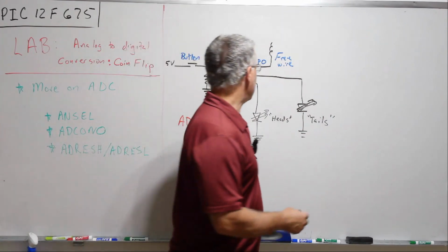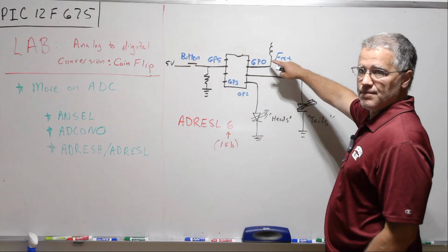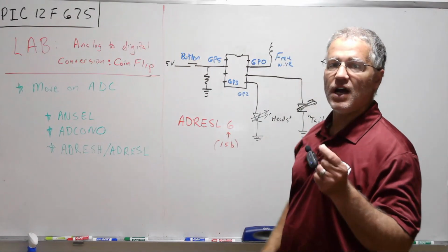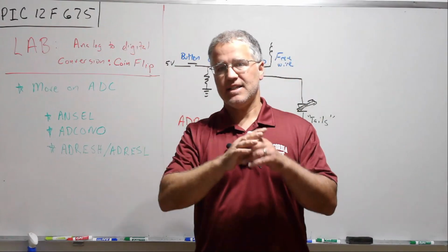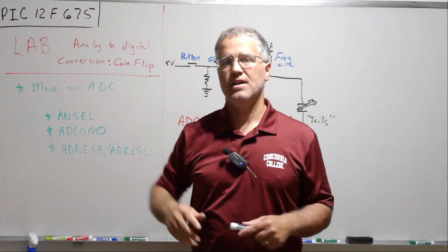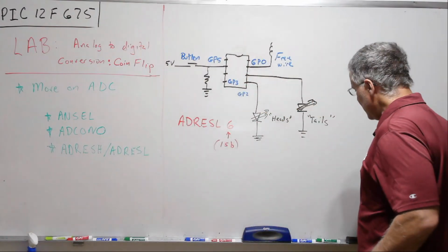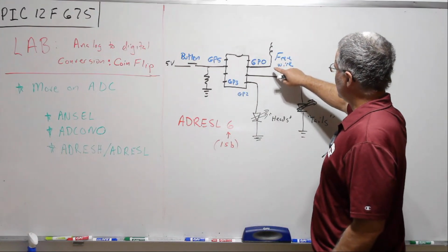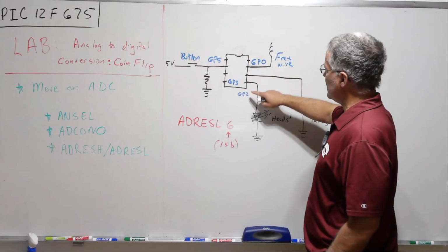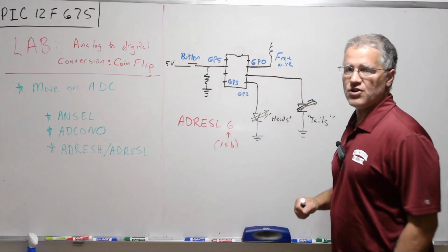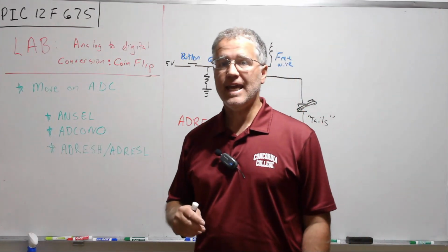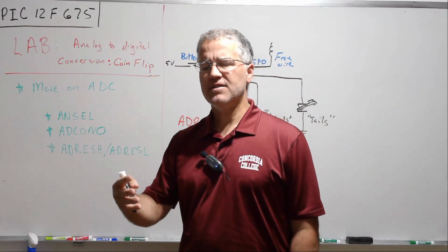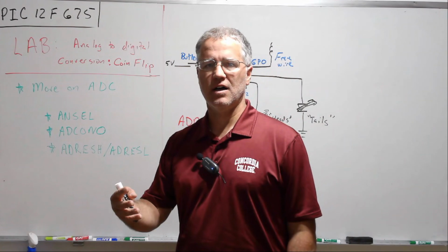So what we're going to do is we're going to just have a free wire, and in fact, just to even improve things, we'll probably hold on to that wire acting as a big antenna, so our voltage is fluctuating quite a bit, and we will read that voltage in with the analog to digital converter, and we will take the least significant bit. So it's very likely that that will be quite random.